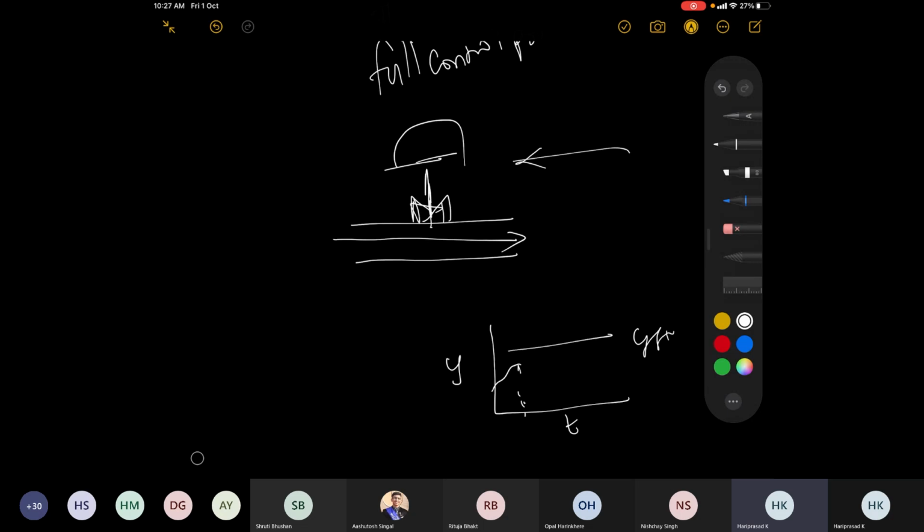But it has already opened its full bore, correct? So this would eventually result in saturation. You cannot do anything. It has given its full power and finally opened the valve, but still your set point has not been reached.